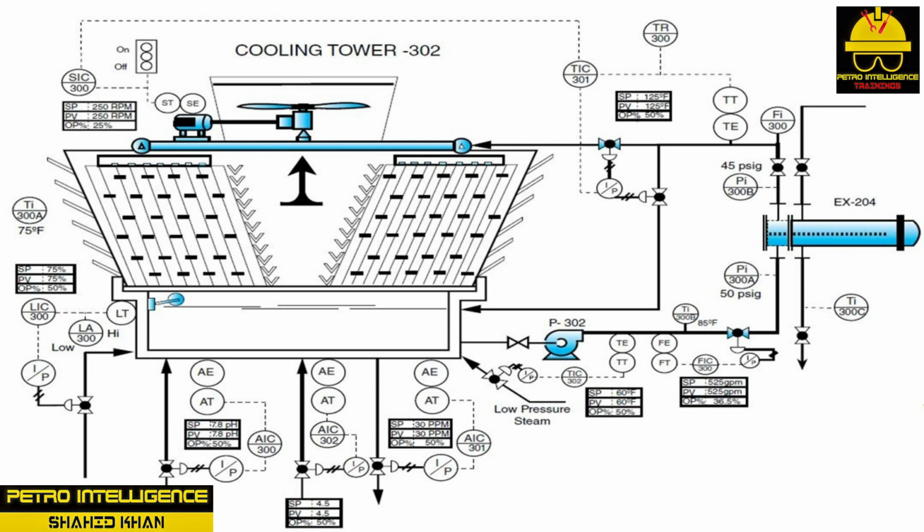High levels of suspended solids will cause fouling. Blowdown is closely related to the term concentration cycles. Blowdown refers to automatically removing 7 to 10% of the water in the water basin and replacing it with fresh water. In most cases, the water makeup system runs continuously due to evaporative losses, drift losses, and draw-off.